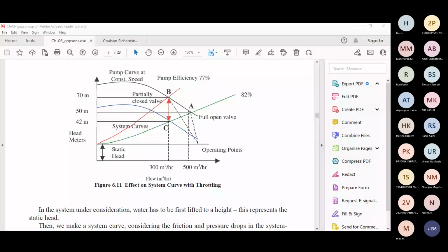So I think your question is, suppose your pump is there and your flow rate keeps on changing because there is a control valve. In that case, your system curve or your operating curve will keep on changing, right? So what you can do is give a recirculation line in that particular case. Using that recirculation line, there will always be some flow rate. Is it clear now?